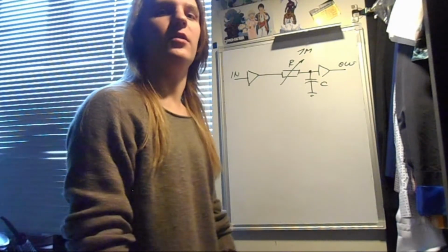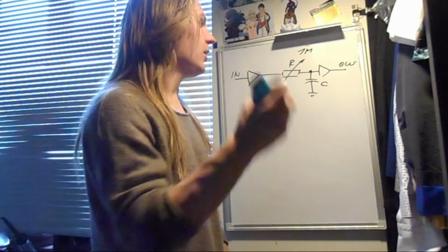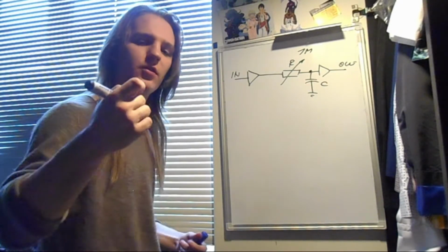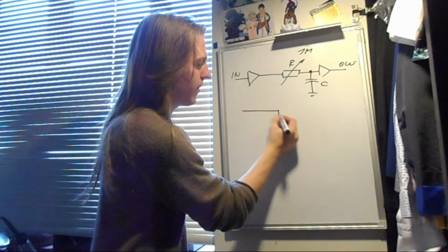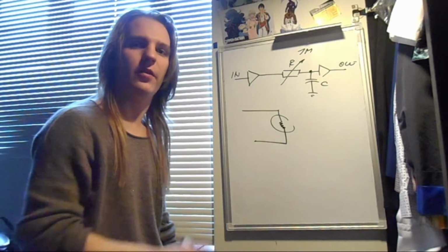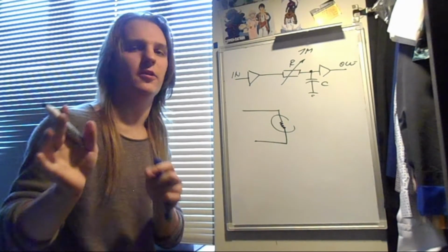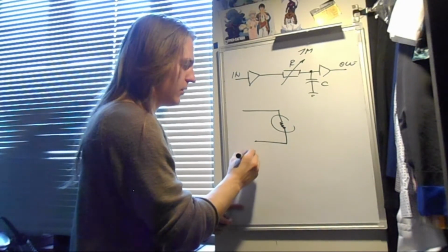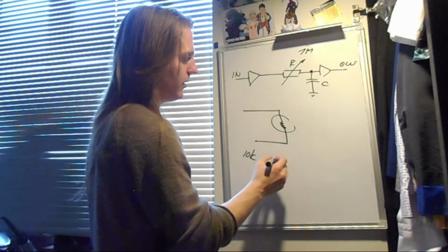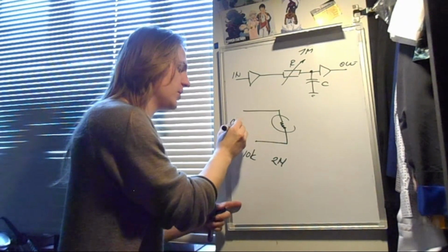We're going to go with a DIY solution because we're Synthcrap, and that means we make synthesizers out of crap, and we're going to use a Vectrol. What is a Vectrol? A Vectrol is a very simple and straightforward thing. We have our optoresistor right here. What it does, it changes the resistance depending on the light around it. If there's a hell of a lot of light around it, its resistance is somewhere around 10 kilo ohms. If this resistor is put into a dark box, then its resistance is something like 2 mega ohms. This resistor's model is GL55.